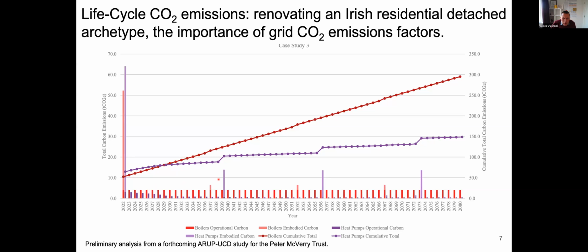And we also may note here that the heat pump is set to be replaced every 17 years and the boiler every 15 years. Those values can be played around with, given industry norms for a boiler might actually be 20 years and a heat pump 15 years. So we end up with a far closer alignment of these two lines after a period of about 15 years.